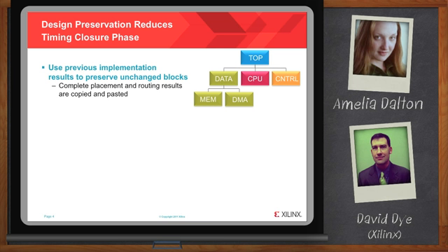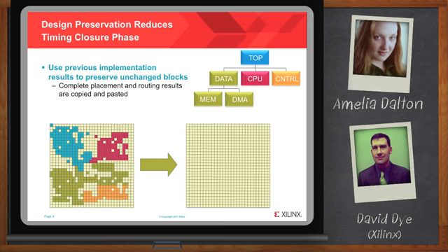These partitions can be evenly distributed throughout the design, or you could simply have one small partition on a particularly challenging block. The choice is yours. So then, once we've established the structure, when the implementation tools are run, the delineation of these group modules is maintained. Now, floor planning is not required for design preservation, but it can further direct the tools to place this related logic together.